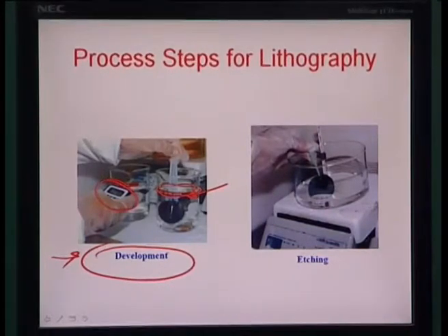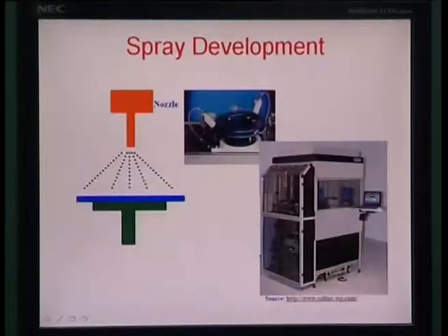You cannot overdo the time part, otherwise the resist starts coming off and you may have inaccurate feature sizes because of under etching or over etching. Therefore you have to critically examine the development process and find out the optimum in any photolithography, and then you can use that layer as a masking layer to etch off silicon and then strip off the photoresist later on.